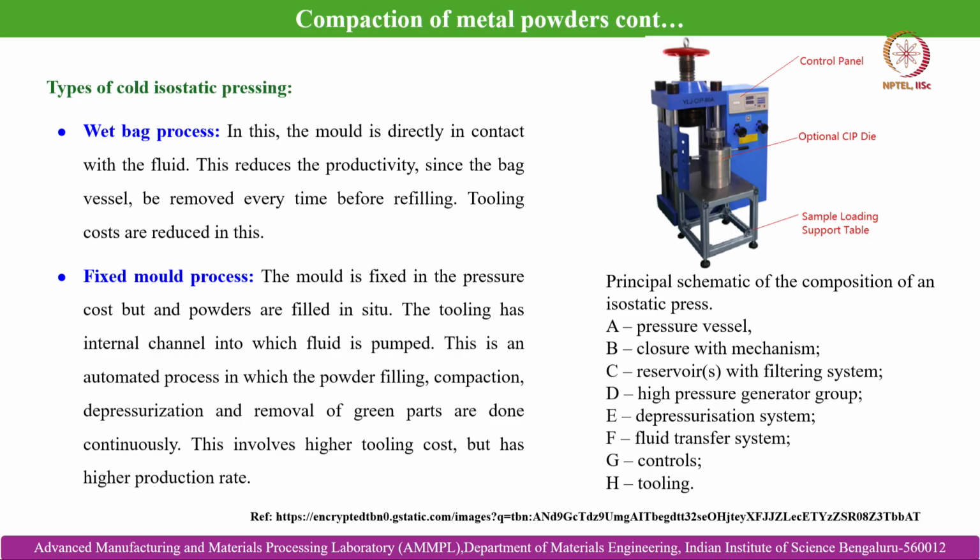So, in this case the mold is fixed in the press, but powders are filled in situ. The tooling has internal channels into which the fluid is pumped, and thereby the fluid pressurizes the powder aggregate which is kept within the mold. So, this is an automated technique in which the powder filling, compaction of the powder aggregate, depressurization, ejection and removal of the green parts are done continuously. So, this involves higher tooling cost, but has a higher production rate as well compared to the wet bag based cold isostatic